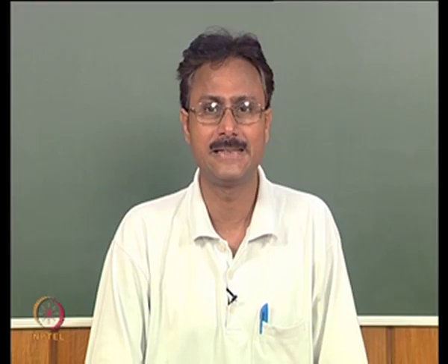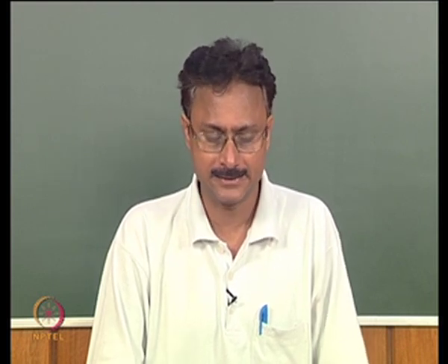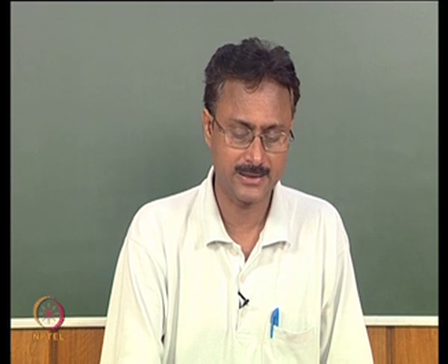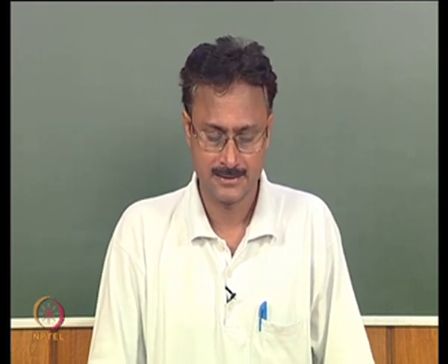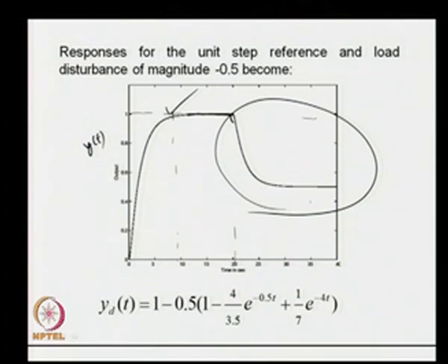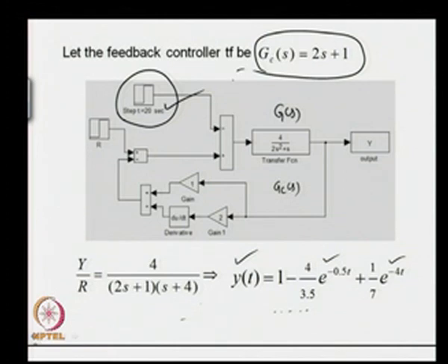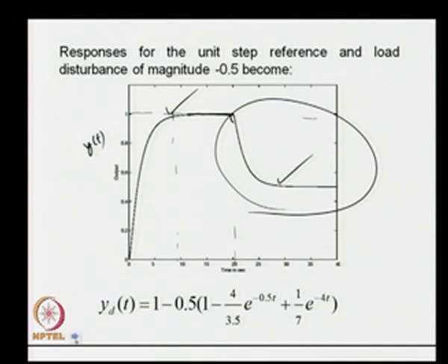PI controller for the integrating process resulted in undesirable set point response, and PD controller also yielded undesirable disturbance response. The earlier two, series and feedback compensations, are found to be insufficient for us, since we are not able to get desired set point and disturbance responses.